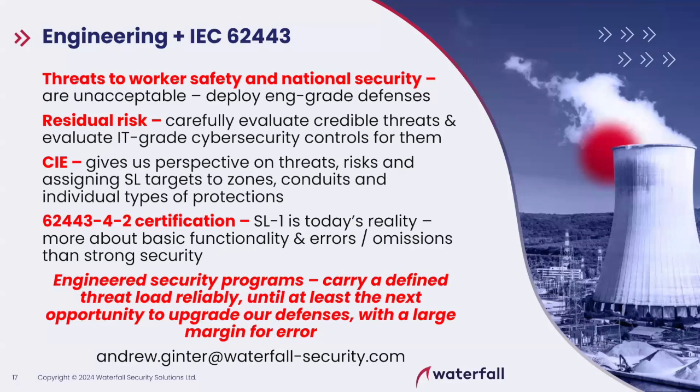If, on the other hand, you have network engineering in place and the bad guys simply cannot get into the OT network, now you're dealing with insiders. Is it credible that an insider is going to deliberately misoperate the safety system? If it is, you need protection in place that addresses how capable that insider is. And so the answer is, it depends.